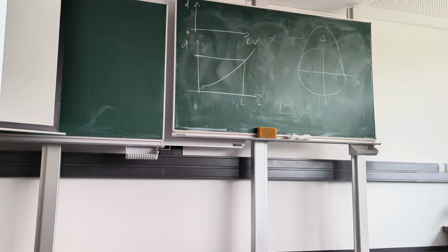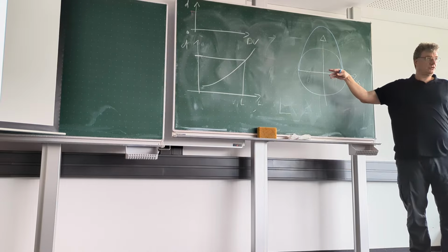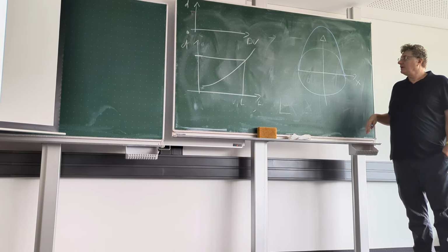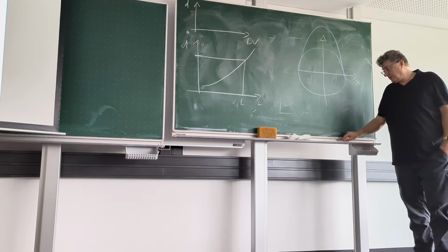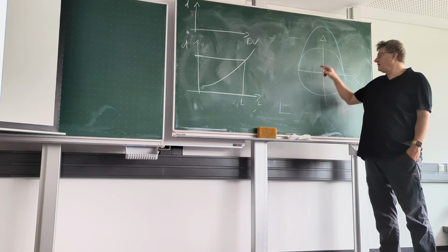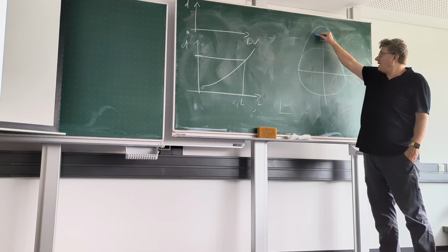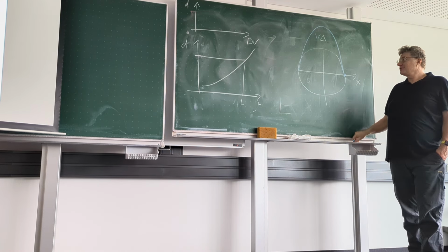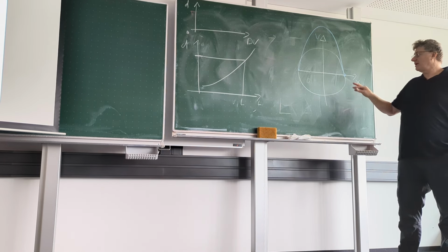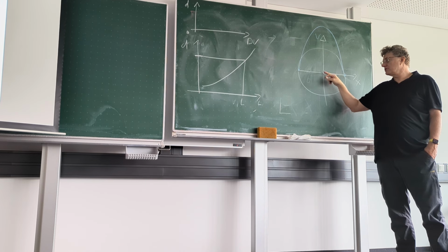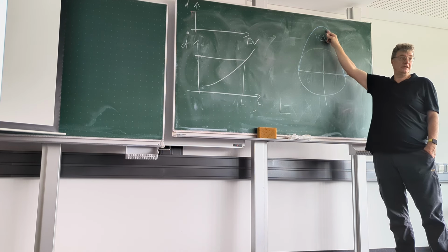And now if you think about how the mesh should be generated, maybe you could be misled and say, here in the middle you have the highest velocity. Maybe I should label it with velocity. So maybe you might come up with the conclusion you need most fine mesh resolution in the region where you have the highest velocity.